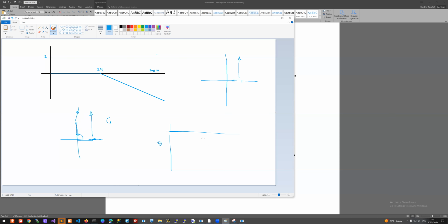So this one will come down to a 90. That's the angle part of the Bode diagram for this particular function. Any questions or comments there? And the location of this is, of course, where omega is 1 over tau, just like we had for the log modulus.